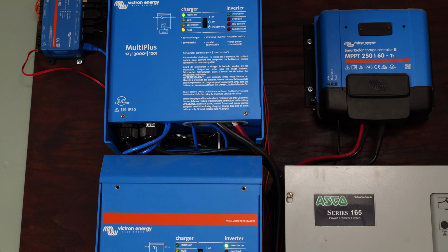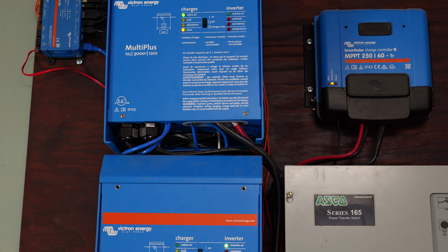In this case here, we have a split phase system, and you can see that they just switched to grid connection and began charging, or in this case went to float as the batteries were full. But this is the first data point to observe: what does the inverter think it's doing and what state does it think it's in.